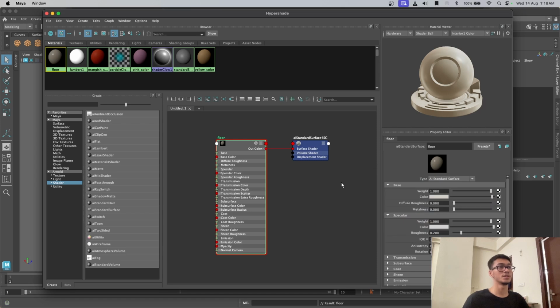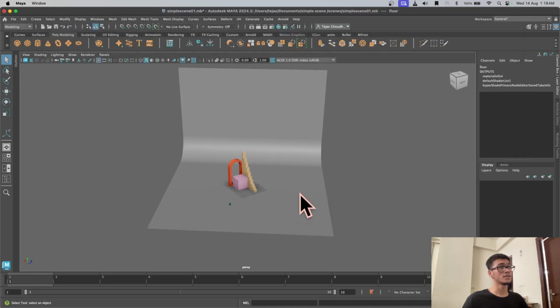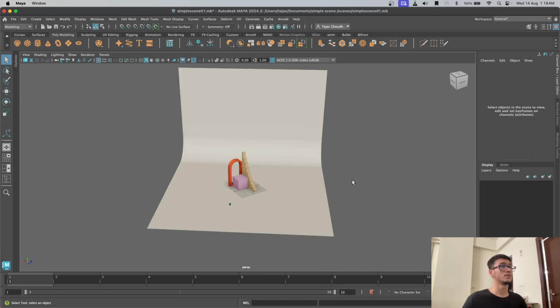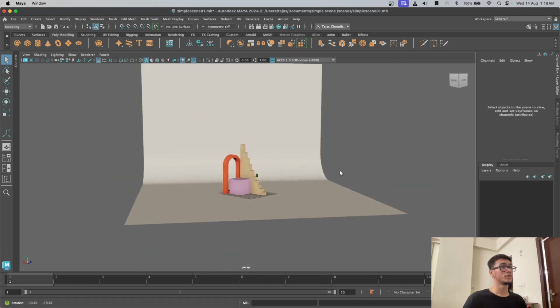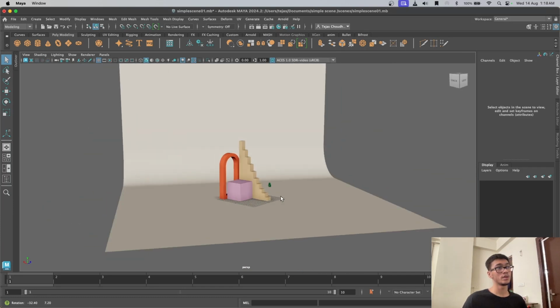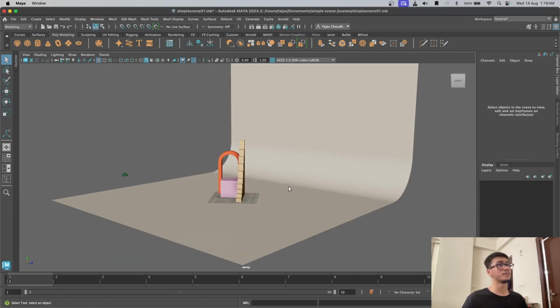It's a lightish yellowish color. Roughness. Okay, so decrease the specularity. Assign the same material to the existing floor. It will be looking like this. It's just our viewport, we are seeing it from a viewport. The render will be different from this.